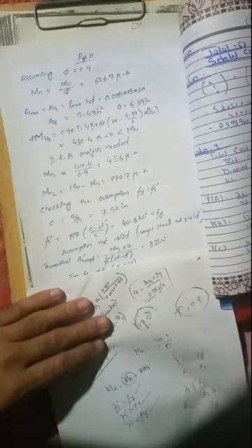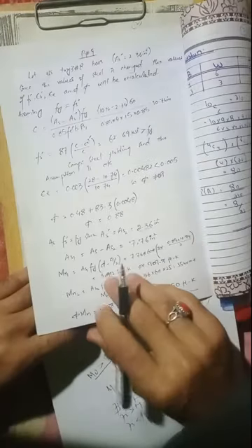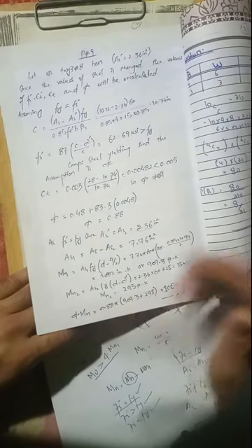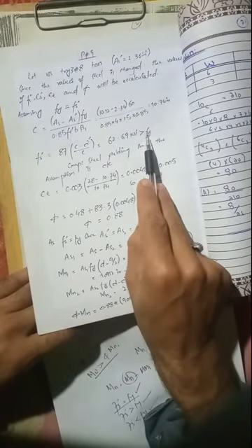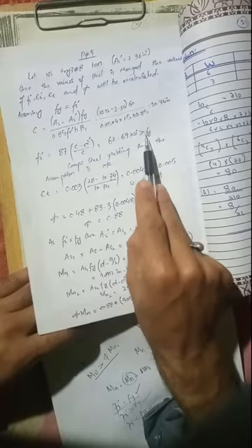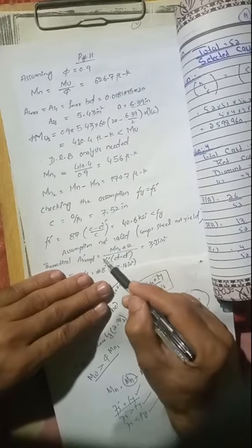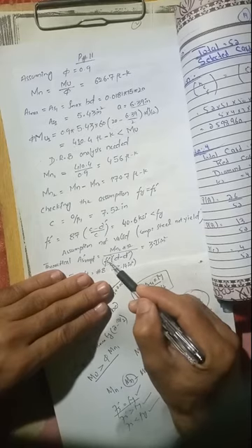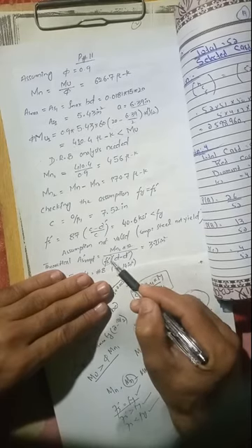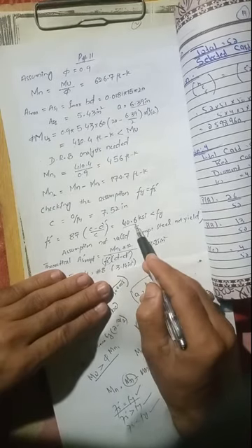Remember, in other examples, let's say in example number 10.9, when we were calculating the As prime value, As prime equals As2, so we don't need to calculate because fs prime equals fy was already satisfied. But if it is not equal, remember, then you can't use fy here. You have to plug in the actual value. Remember, this is very, very important, right? You have to use the fs prime value, not the fy value, so you have to plug in the actual value, that is 40.6, not the 60.